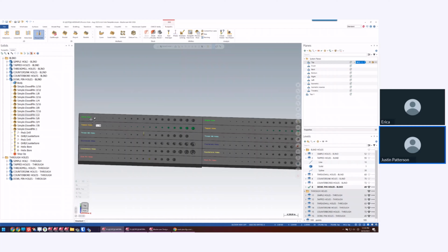And I helped them build a template for it. And literally their programming, what was taking them a couple hours doing all this, they were doing in under 10 minutes because they were always putting in these threaded holes. They were always putting in these counterbore holes. They were always doing this, that. And so if you don't want to build a template this exotic to where it has all of this stuff, just build it big enough to do what you're doing.